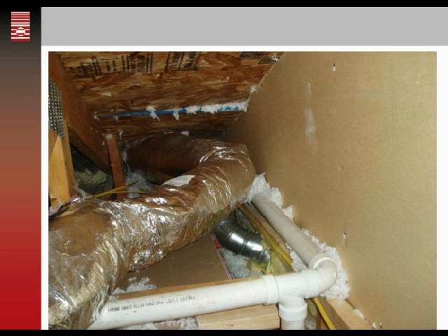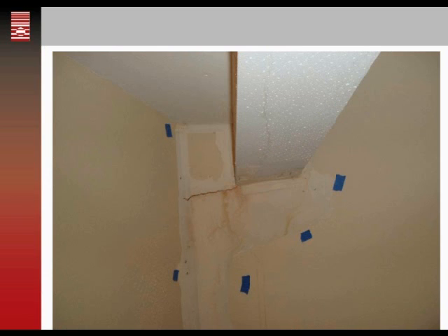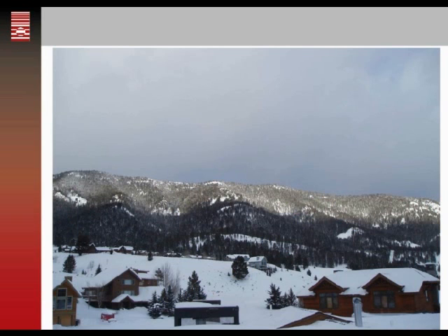So now we've got one going down the back, one coming up from the front, one coming up from the back, bringing cold air from the outdoors up into the attic space to help keep the space close to the temperature and relative humidity of the outdoors. And once we disconnected this duct, you could feel really cold air from the outside being drawn up into this space. So it was very effective at getting airflow up into this attic space to help align those pressure and thermal boundaries. Just a little bit of the damage that was occurring there.